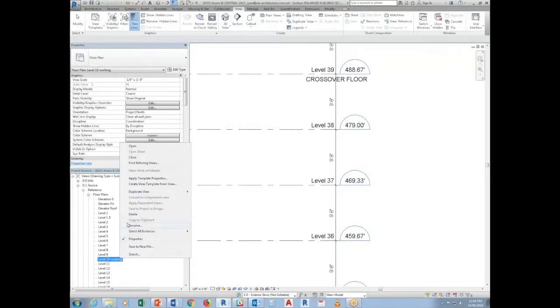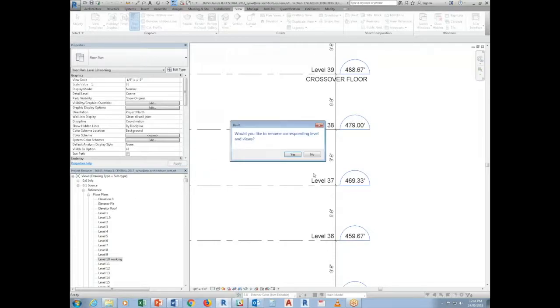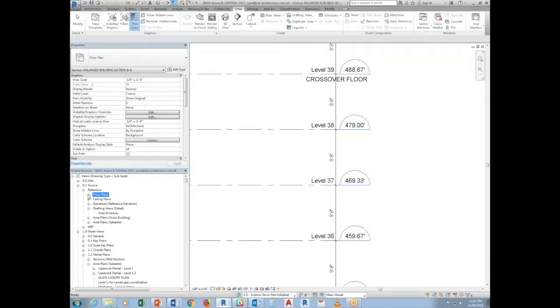Yeah, hopefully that helped you understand how to approach working views in the future: we have all the source views. So if you created 50 floors, then you're going to have 50 levels of that. I basically create all the source views, the working views, inside this, and also do it for ceiling as well, and all the area plans as well. So anything that you're creating, because the level itself is very finicky. The minute that you start renaming one of these, it will rename that. Even a ceiling plan. If you rename a ceiling plan, someone will accidentally do that.